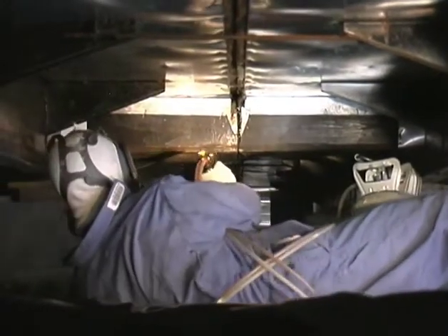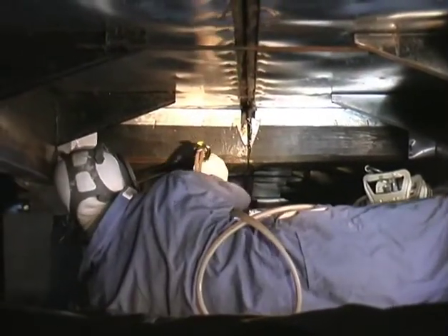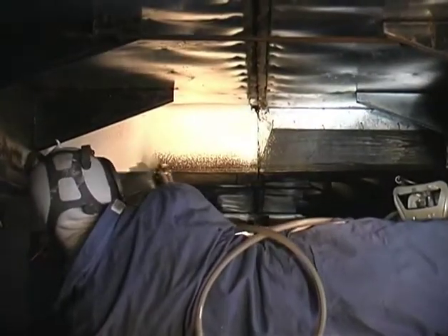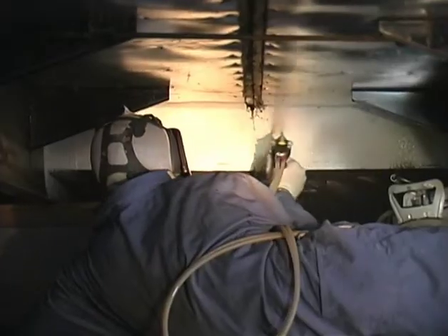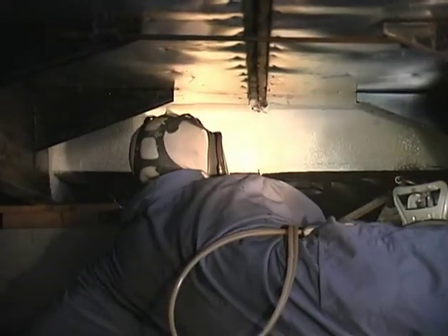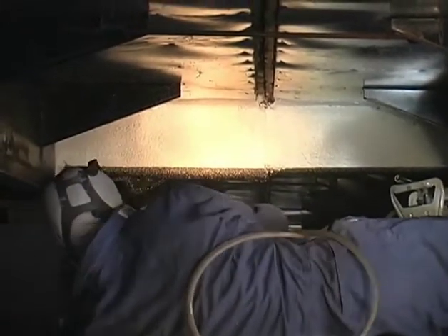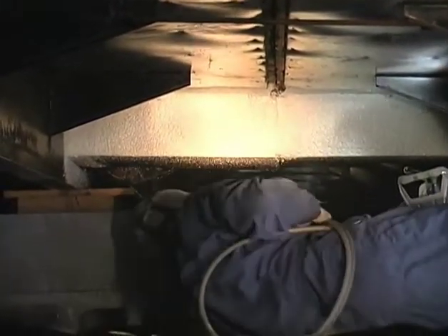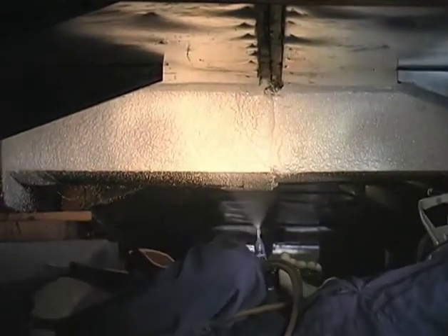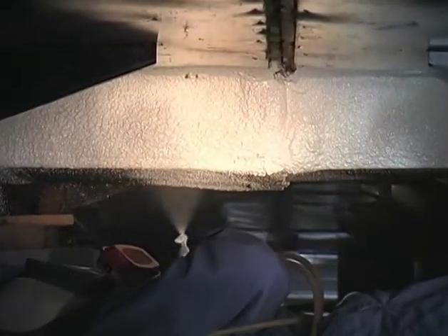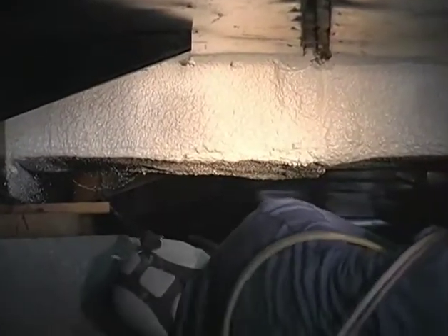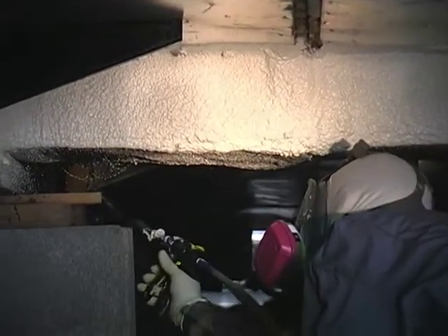Lee's going to go ahead and actually seal this trunk line where it leaks. He's applying the 2-part foam. He's insulating the duct and sealing it at the same time. You can still see somewhat of a crack there, but that'll expand shortly and seal up the cracks in the trunk line. Now he's going for the crack underneath. He's also, again, using the foam to insulate the bottom of the duct, which is important also to have an insulated duct.